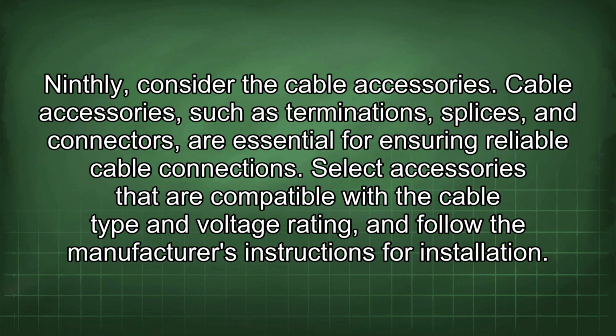Ninthly, consider the cable accessories. Cable accessories, such as terminations, splices, and connectors, are essential for ensuring reliable cable connections. Select accessories that are compatible with the cable type and voltage rating, and follow the manufacturer's instructions for installation.